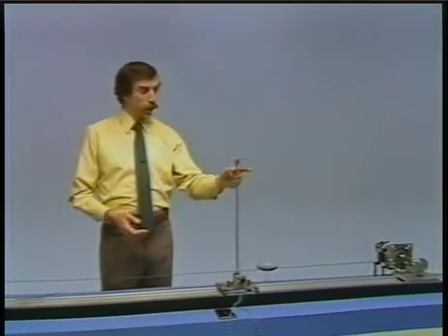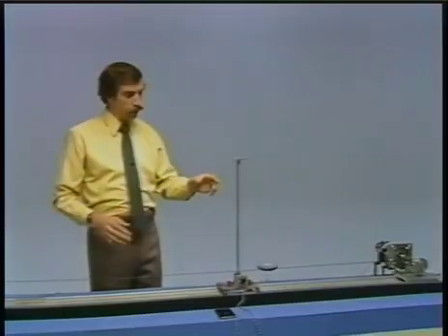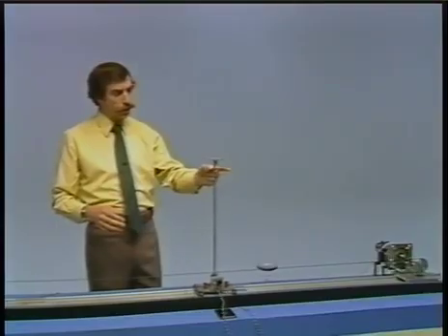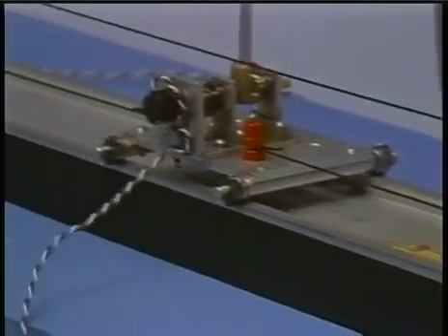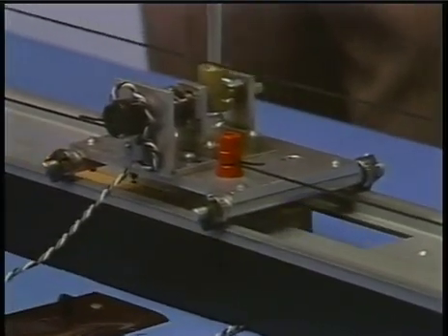Remember that with the feedback off, the system is unstable because the pendulum will fall, whereas now it's stabilized. Now also, as you can see, not only have we stabilized it, but we're able to compensate through the feedback to changes in the external disturbances. For example, by tapping it, because of the feedback and the measurement of the angle, it will more or less automatically stabilize. Now, in addition to being stable in the presence of external disturbances, it also remains stable and remains balanced even if we were to change the system dynamics.